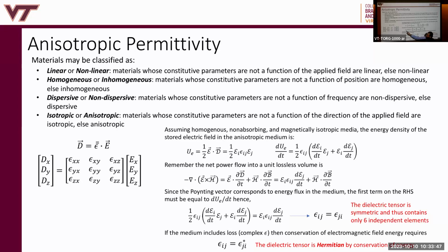So here we have the divergence of E cross H. If I add up all the power flux on some surface surrounding some point and let that point shrink to 0, so we can do this definition at every given point, then that has to equal this number, which has to decay, right? We'll see that. Okay, so power flow into a lossless unit volume. This is our conservation theorem from lecture 1. Divergence of E cross H, the power that's flowing out of a medium, but there's a minus here, so it's power flowing into the medium. So power flowing into a volume, a region, right?